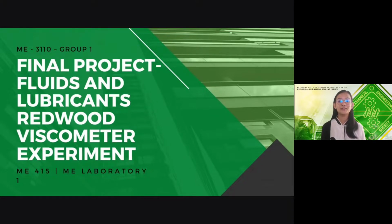And by Newton's law of viscosity, the shear stress between adjacent fluid layers is proportional to the velocity gradient between the two layers. Thus, a proportionality constant of the coefficient of dynamic viscosity is introduced. The formation of a fluid film of a lubricant between the moving friction surface and the generation of the frictional heat under the particular condition of load, bearing speed, and lubrication supply mainly depends upon the viscosity of the lubricant or to some extent to its oiliness.